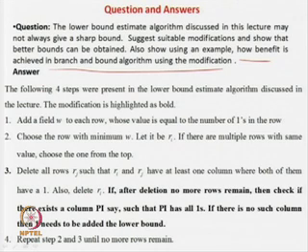Because in the lecture flow we have seen that the bound was a bit loose, that is your bound was giving 1, and then it was 3 plus 1, 4. You were prone to explore further, but finally you find that the cost is 5, and you are then higher than the initial cost, and you have to explore the full space. And then you will find out that nobody can give a solution in less than 5. So the answer is 5 prime implicants, and you take any one of them. So unnecessarily you have to explore the whole tree.